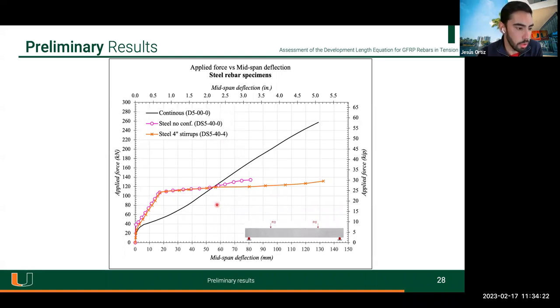contribution to that. Also, you can check the difference between the structural behavior at the same load. Here we have only a deflection of around 18 millimeters, but the one of FRP has around 55 millimeters of deflection. So we have more deflection because of the low modulus of elasticity, but the final capacity is way larger than the previous one.